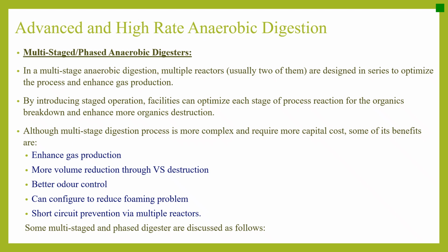Although the multi-stage digestion process is more complex and requires more capital cost, some of its benefits are as follows. Enhanced gas production, more volume reduction through VS destruction, better odor control, configuration to reduce foaming problems, and short circuit prevention via multiple reactors. So some multi-stage and phased digesters are going to be discussed in the following slides.